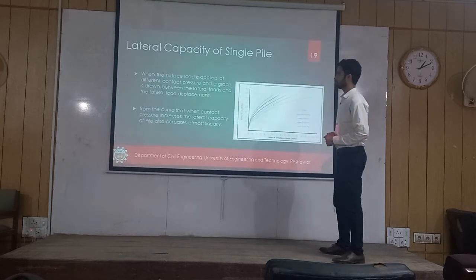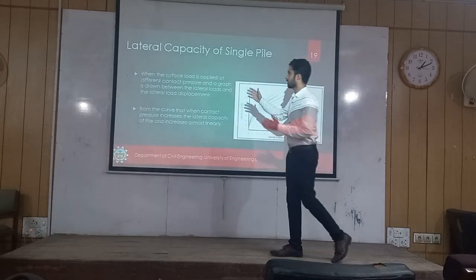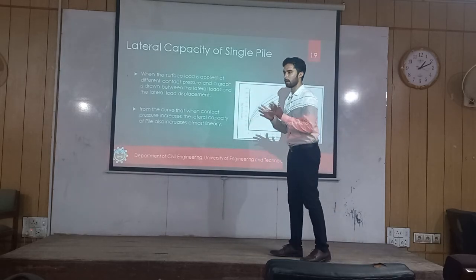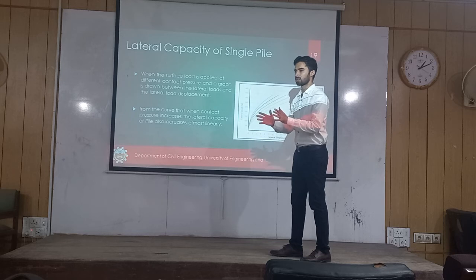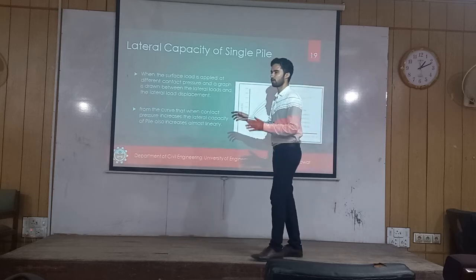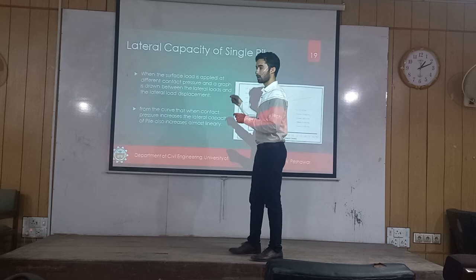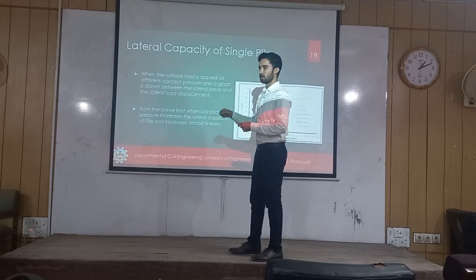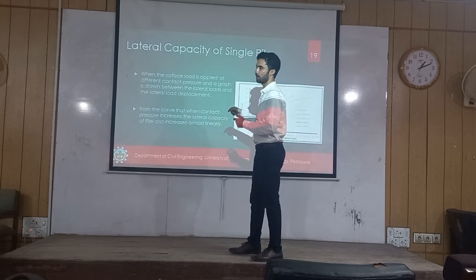Next please. So we come to this point that when the surface load is applied, the contact pressure increases. When the contact pressure is increasing, the strength of the pile is increasing. When the strength of the pile is increasing, the displacement is reduced. This is what we find in our experimental data, that if we consider this contact pressure in design, it will be more economical.